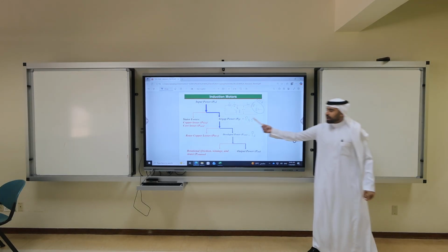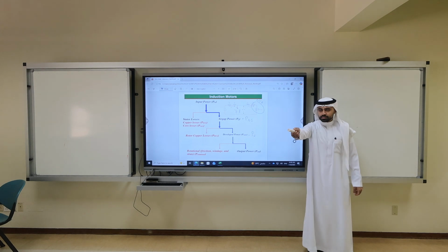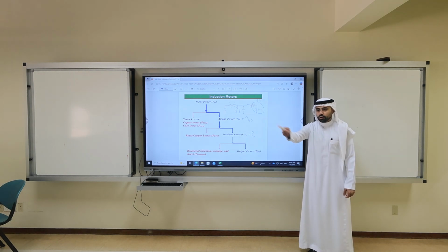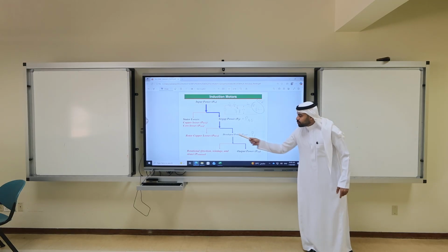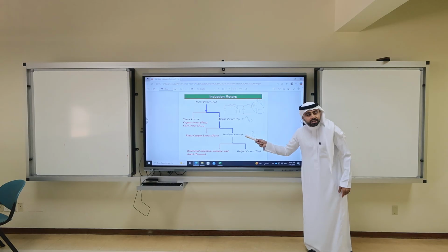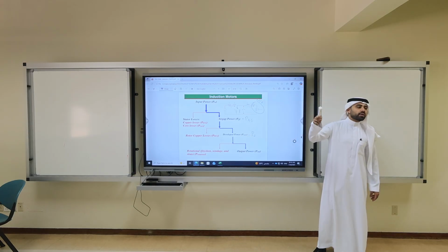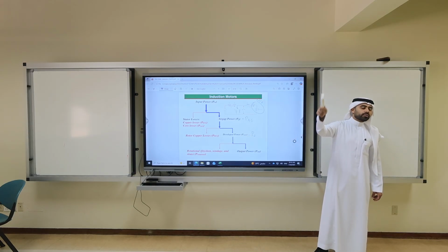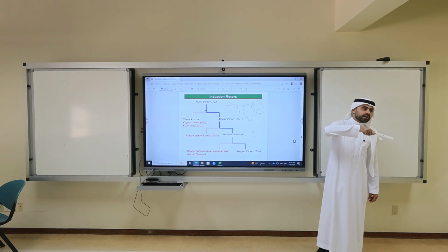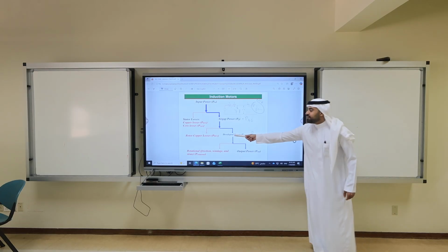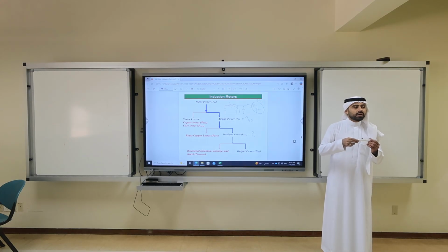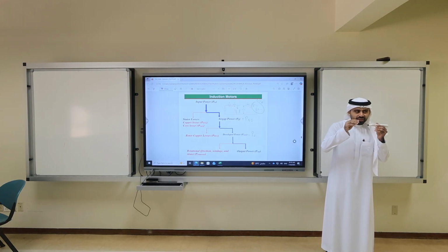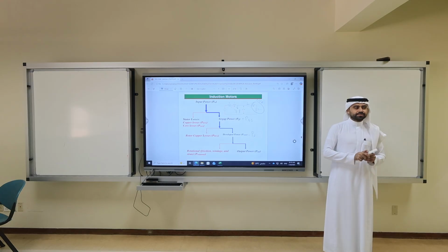It's easy to know: G is AG, air gap. Does it matter? Doesn't matter. The developed power, people call it converted because it is the converted power from electrical to mechanical. Or they call it developed power. Developed power where? Not at the shaft, just before the shaft.